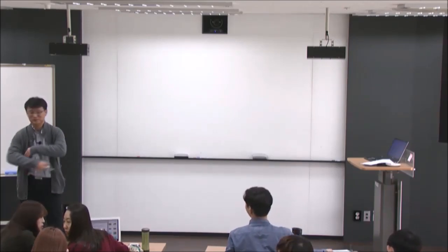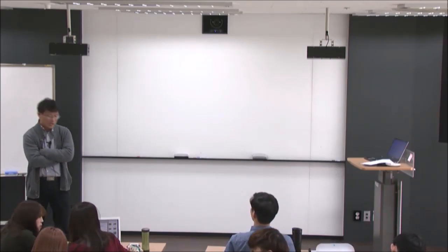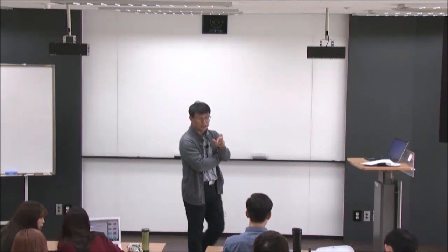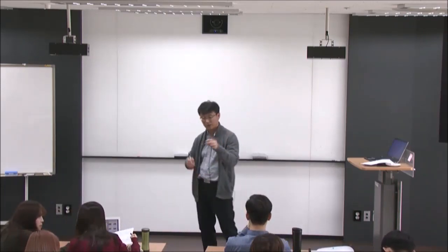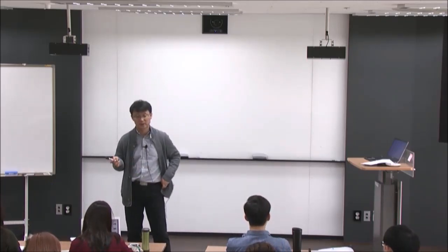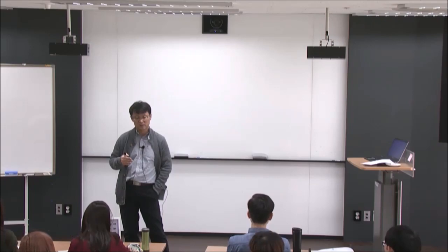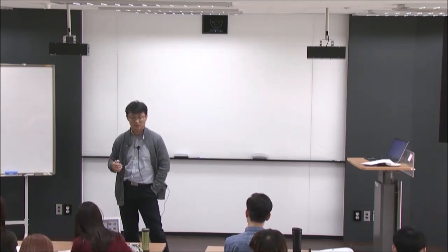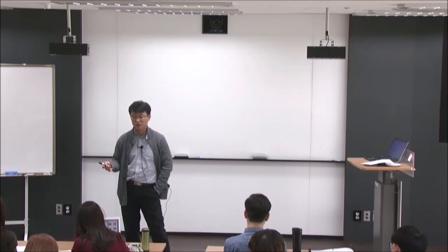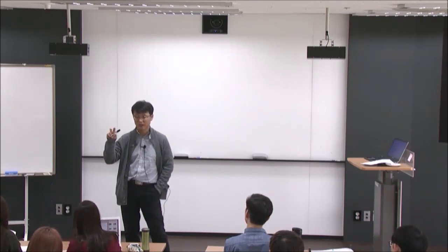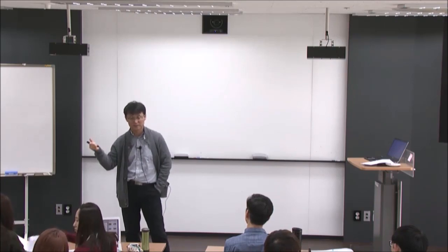Now, today we're going to look at this oxidation reduction reaction in a little more detail. Especially when you have a metal reacting with oxygen and becoming an oxide, at a given temperature, what would be the minimum partial pressure of oxygen which makes that chemical reaction happen?